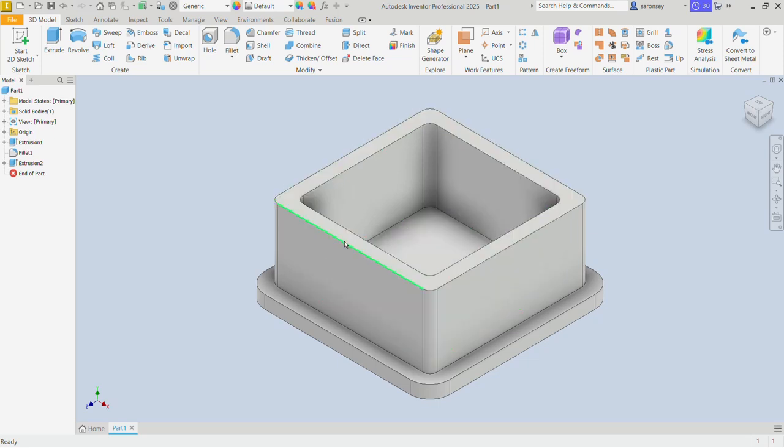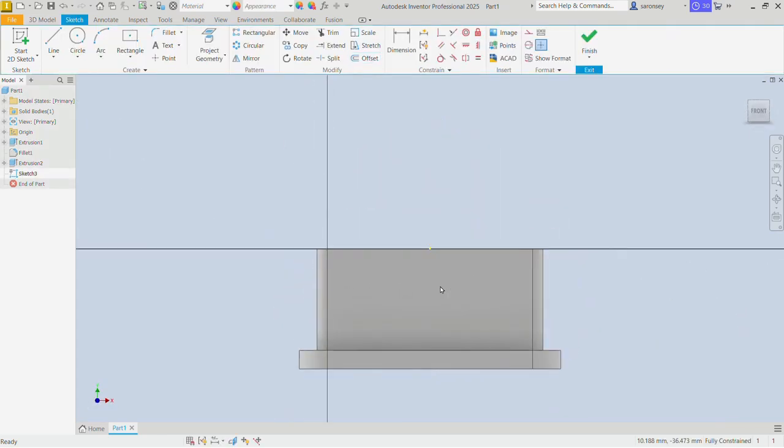Now we want to create those holes inside which we would be placing our bearings. And so select this face and create a sketch on there. Let's now pick the circle command. Let's draw a circle at this point, which is the midpoint of this very line. And so I will draw. The diameter of this circle is 80. Let's type that and enter.